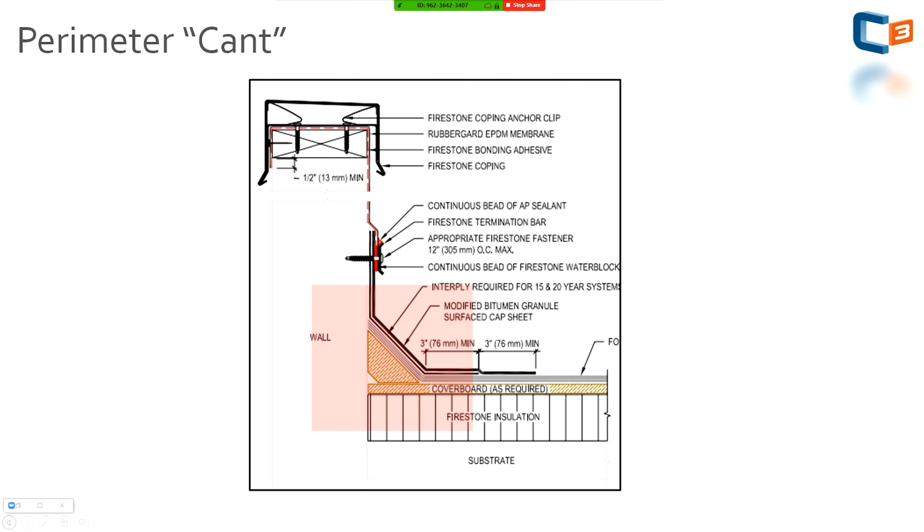So here's a design spec basically showing the parapet transition. This is also applicable to curbs. Generally, when you have built-up or modified bitumen roof systems, you're going to have the transition between the field and vertical walls or curbs. There's going to be something called a cant strip. Over time, the membrane in that area, outlined in red there, will pull away from that cant area. Especially with older roof systems, this might be very well supported at install, but 20 years down the road, sitting in the sun, especially in Colorado sun where I'm from, this is going to break down. So you're going to find an unsupported area there where there's just a little void. If hail impacts that, it's totally unsupported, and you're generally going to find damage there first.